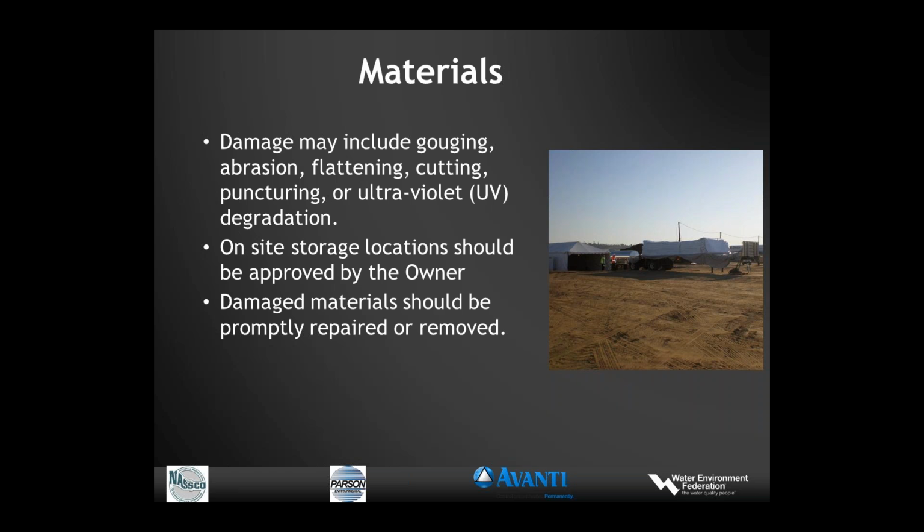The photograph here shows a cured-in-place job site. This is a large job with a tube. You see a tube on the flatbed trailer there, and immediately to the left of the tube is a portion of a 5,000-gallon resin tanker. These are materials that have been shipped to a job site. The tent contains a wet-out conveyor. That's where the vacuum impregnation will take place. This tube and resin combination is much too large to transport down a highway, so everything happens on the job site. But this is where observations of these materials, inspections can take place.